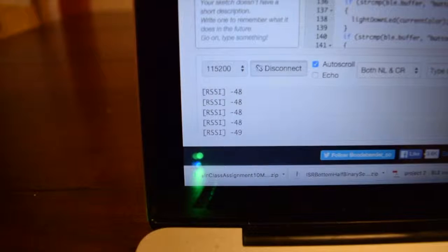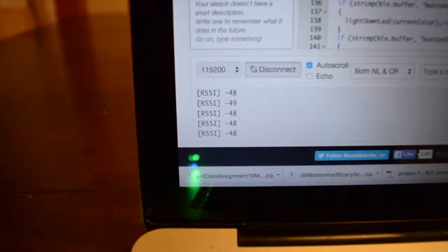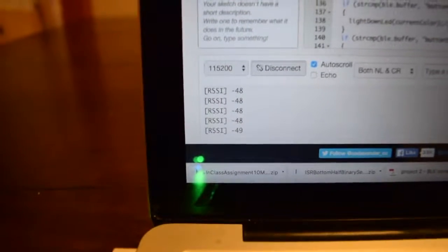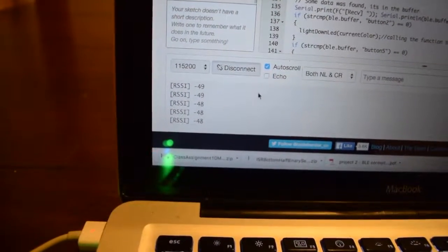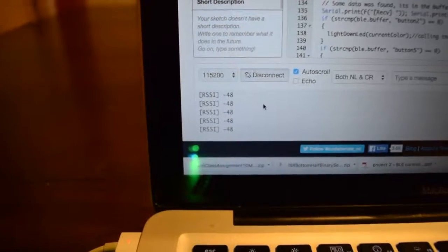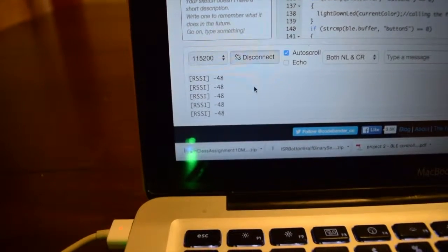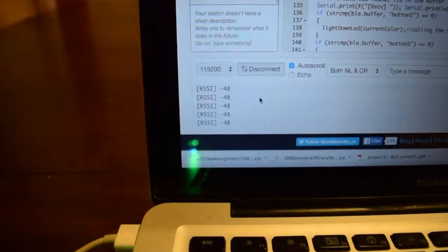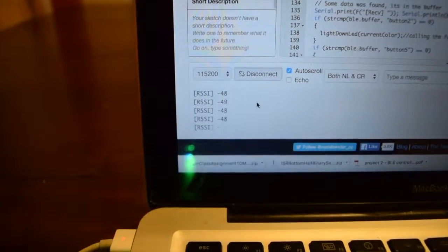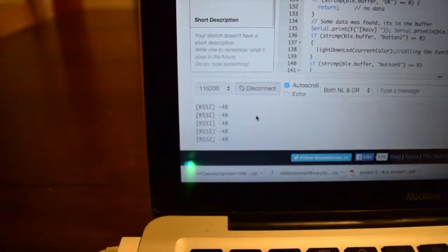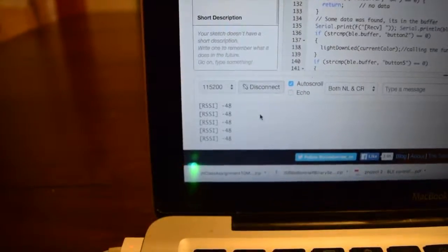This is how the system works when the phone starts leaving the proximity. The system is configured to present the intensity of the Bluetooth signal. Right now it's presenting this information, and to reduce the bouncing of this connection, I'm using an array of 30 values. Once the array is full, it's getting the average of those 30 values.